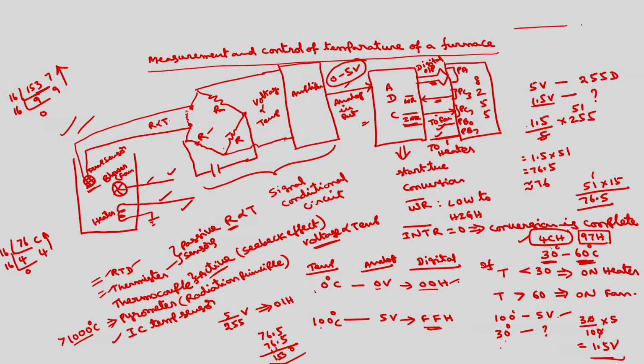If you want the control register in I/O mode, this is for port C lower. Port C lower we are using as an output port, so this will be 0. This is port B; port B also you are using as an output port, 0, and this is the mode selection for port B. I am using mode 0.